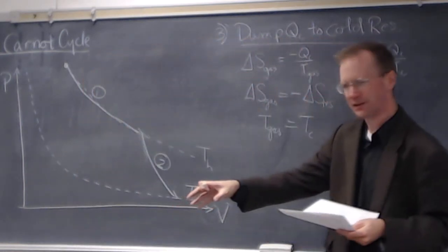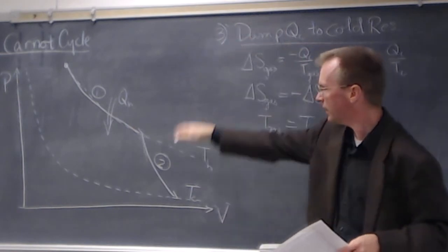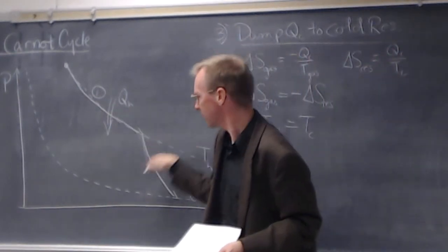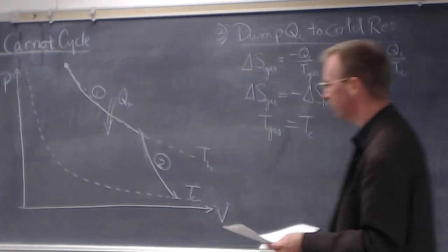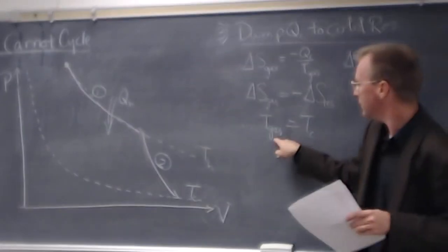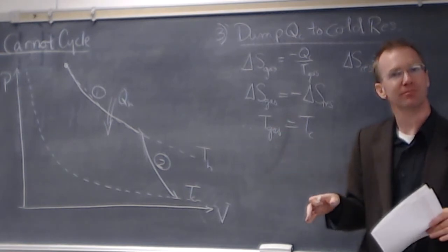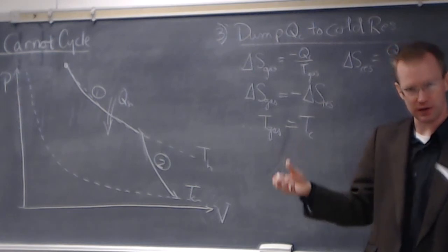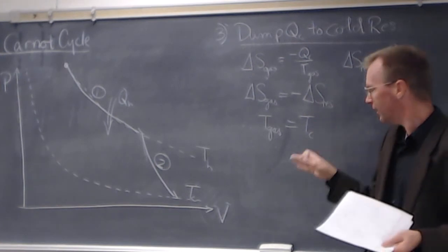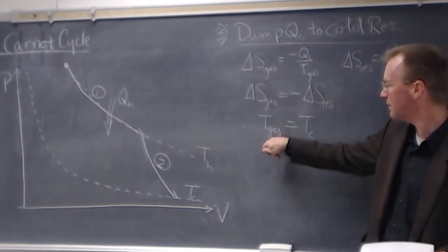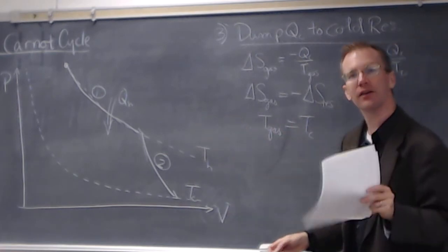As the gas loses heat, I can kind of draw here. There's our input heat coming. Let's think of this as being inside the system. We're going to make a closed loop around here. It's a convenient way of diagramming it. Now, at this cold temperature, we're dumping the waste heat. How do we do it? If we held the gas at a fixed volume, as heat flows out of it, the internal energy would decrease, and if we're not doing any work on the system, its temperature would go down. But we can't have that because the heat won't flow. So we've got to maintain the gas's temperature infinitesimally above Tc while it loses heat, which means it has to be compressed. An isothermal compression.